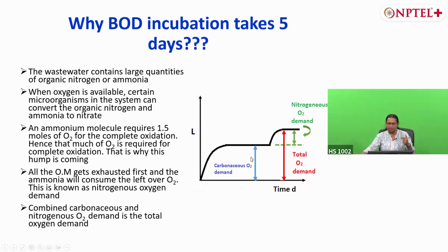Mostly BOD5 we are doing during that time, so most of this carbonaceous oxygen demand will be taken care of. If you go further, this nitrogenous demand also will come into the picture. So total oxygen demand will be the carbonaceous oxygen demand plus the nitrogenous oxygen demand.